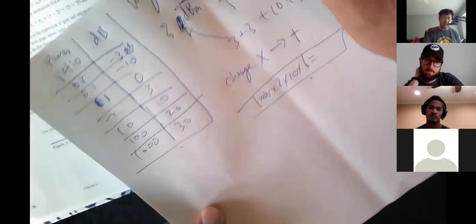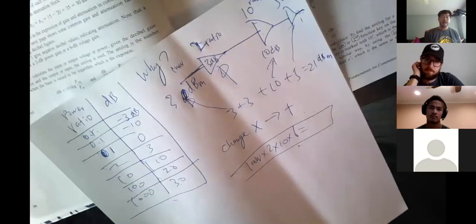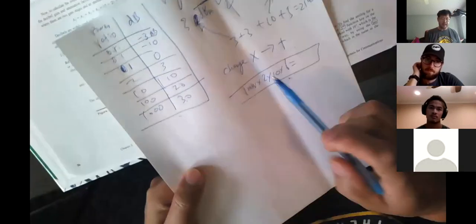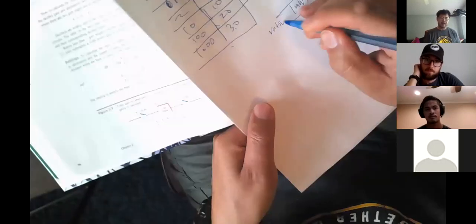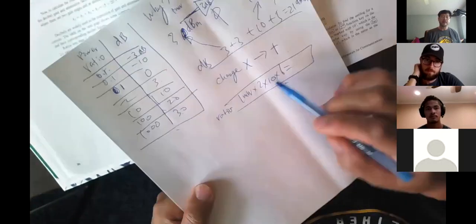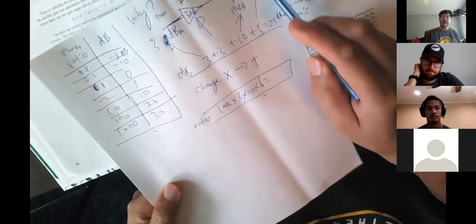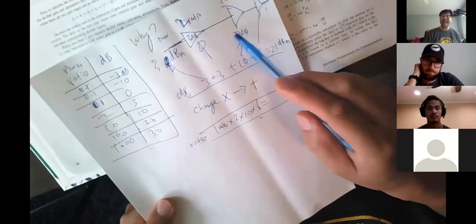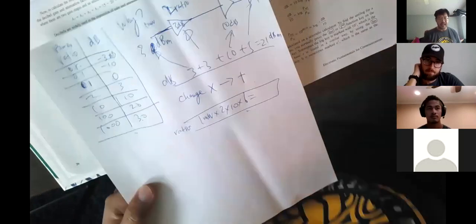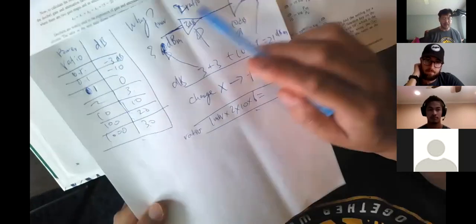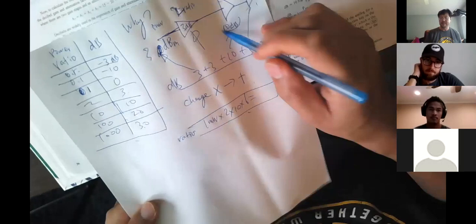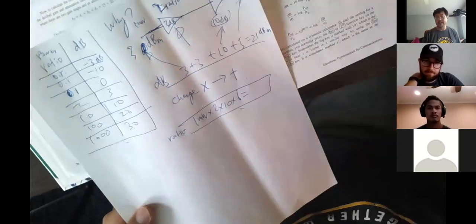So with ratio, if you have multiple amplifiers, you have to multiply. That's the ratio. With decibel, you convert all the multipliers into additions. Add. Every amplifier is another add. So the gain is just add all the decibels together is the gain. The reason is quite obvious.